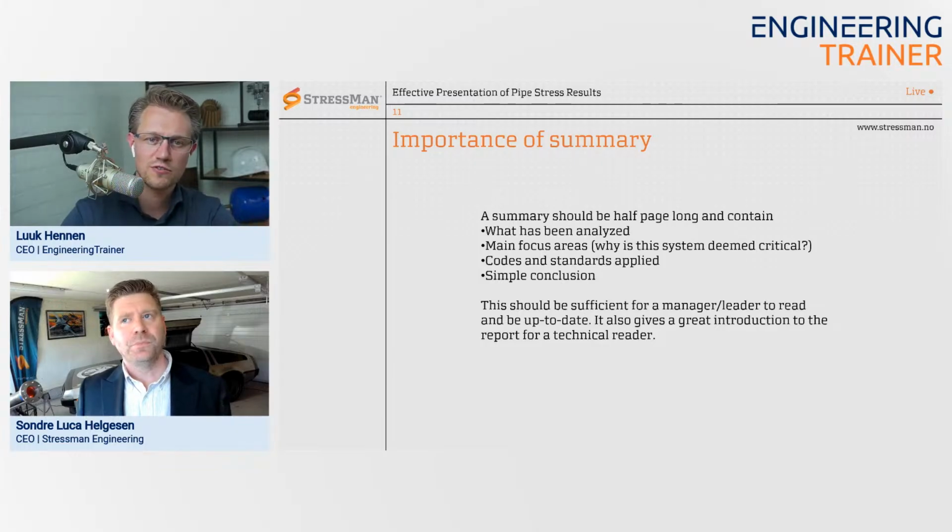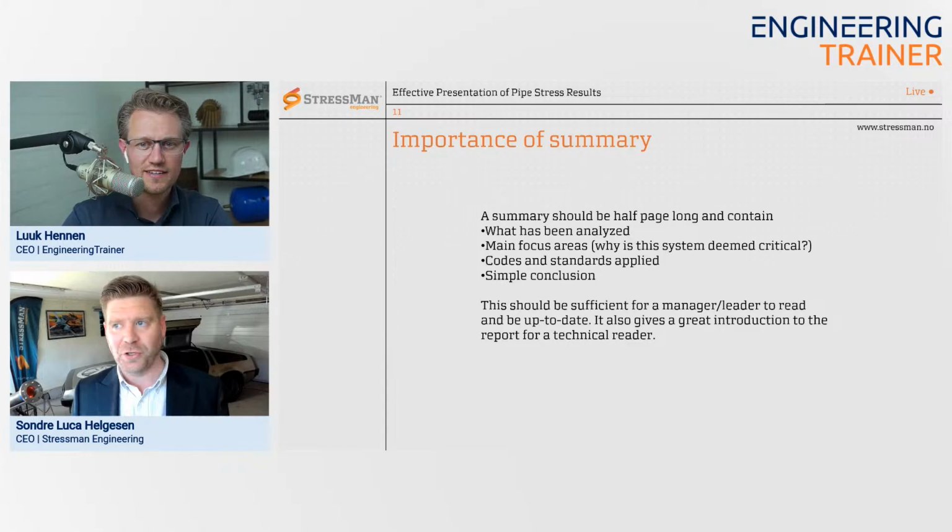It's not that much related to reporting, but how to solve nozzle loads on rotating equipment. Yeah, of pumps. Of course, we all have been there. And usually it's in the middle of the night. You tried 100 million iterations and you don't get a pass. And you really try. And maybe it's only one direction. Maybe it's even a shear force that you feel, yeah, this is not a problem. This is not generating that much of a load on the pump.